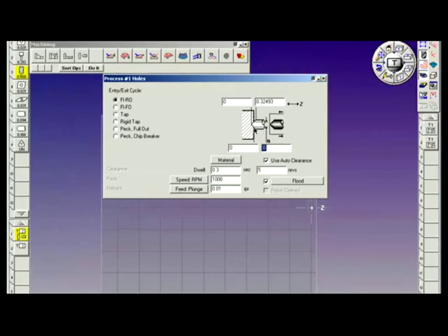The other option is to the tip. I take the depth of cut to the tip of the tool. And the other option is to the shoulder of the tool. So in this particular case, I'm going to take the center drill, a minus 0.275. The other 2 fields update automatically. And this will drill 275 thousandths into the part based on the tip, dwell for 5 revolutions, retract, and go home.